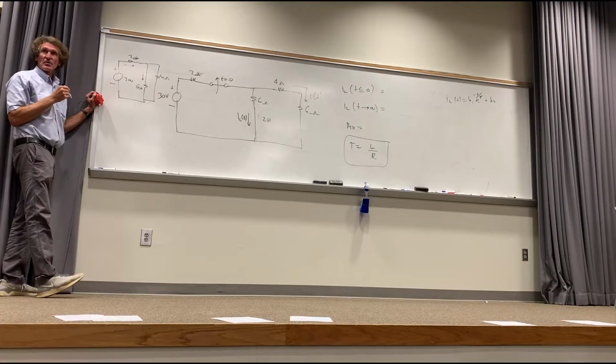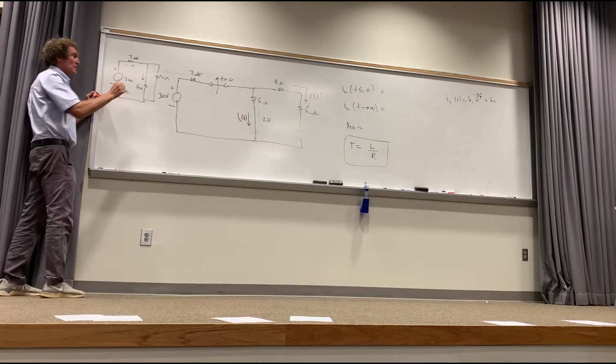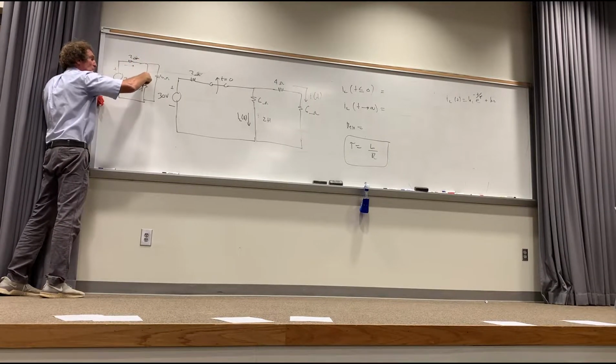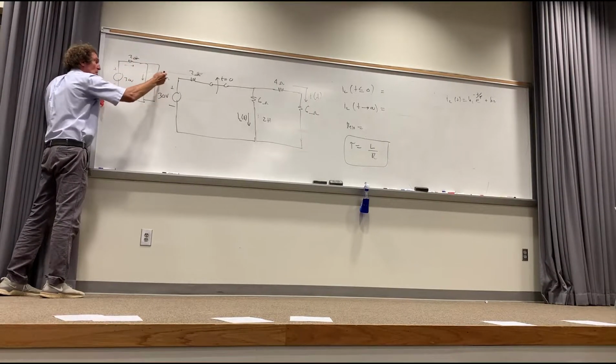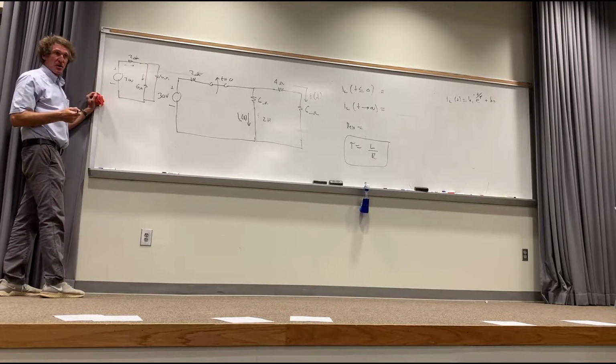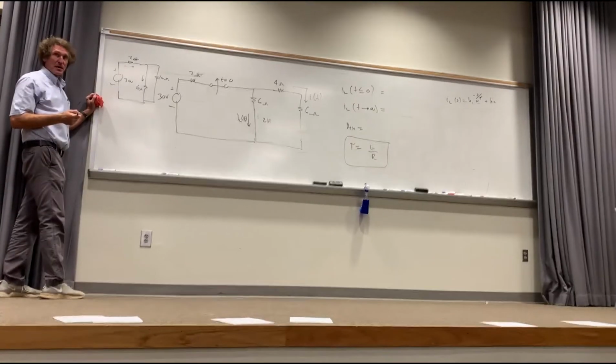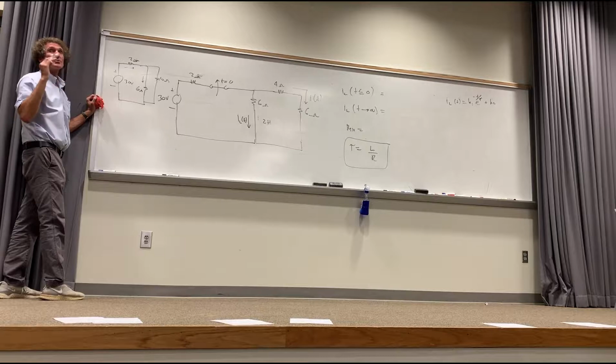And then once I had the current through there, I could say through current division, the current through here would be that current times 10 over 10 plus 6. Do y'all agree with that? You can do it that way. A second, I'm going to just tell you what your choices are.